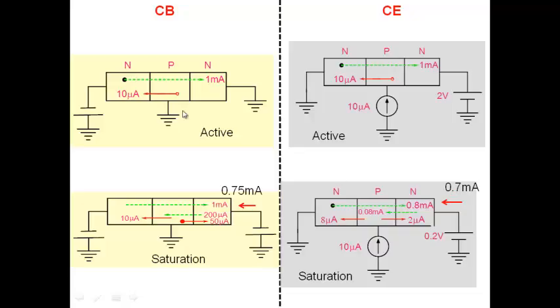Note earlier this was 1 milliampere here, and it stayed 1 milliampere here because we didn't touch the base emitter junction. And the reason why it has fallen to 0.75, this 1 milliampere gets cancelled by this injection from here. But in this case, this 1 milliampere itself has become 0.8. The cancellation is there, but it's much smaller. It's only 0.08. It's only 2. So it's quite different in terms of why the current is falling. The current is falling here because the base current that you see here, which earlier was flowing in the base emitter junction, is getting increasingly diverted here.